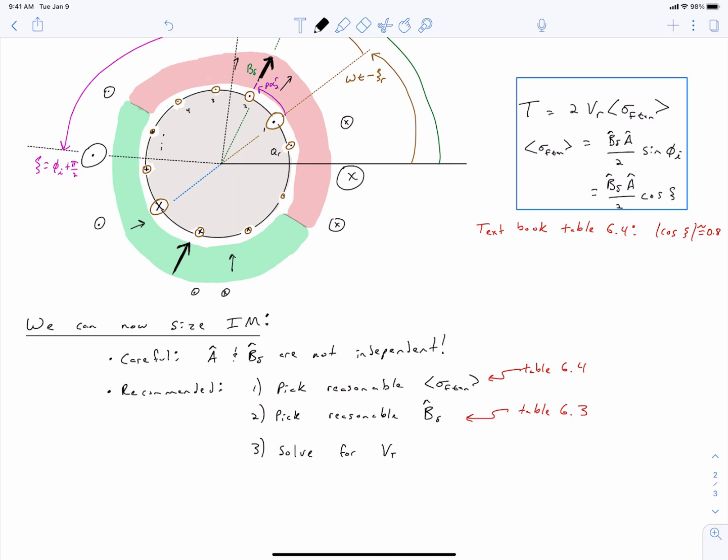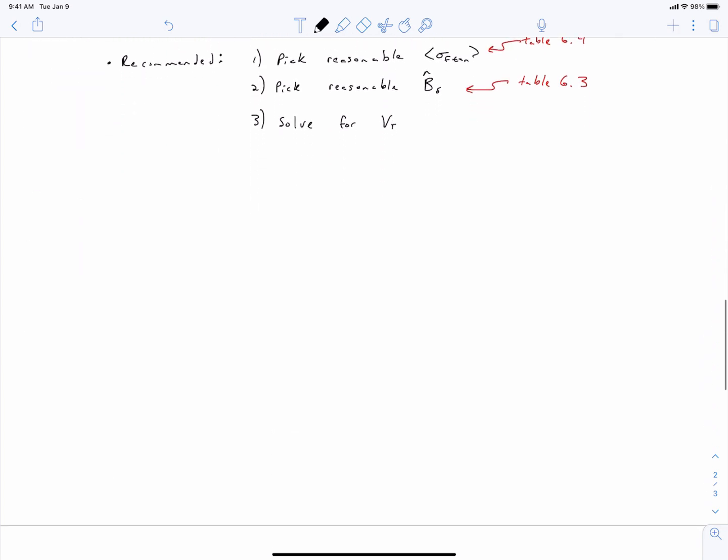In principle, we've talked through how to size an induction motor. However, there's one more important thing that I want to address, and that is how power factor relates to all of this. And so let's go ahead and discuss that, and let's discuss it in the context of a case where under rated conditions, our rotor impedance angle is 0. That is, our rotor appears nearly perfectly resistive under rated conditions. And for a lot of machines, this is a reasonable approximation because at rated speed, your slip is fairly small. Maybe it's 1%, maybe it's 4%, but it's a pretty small value.